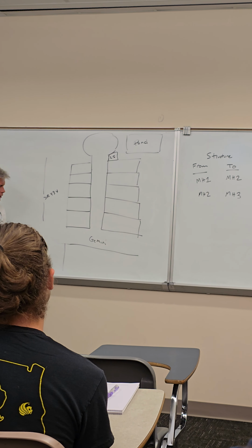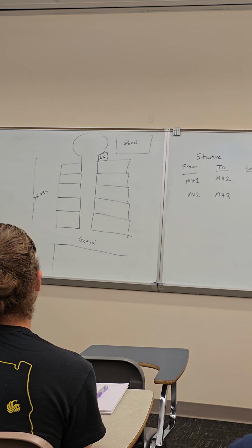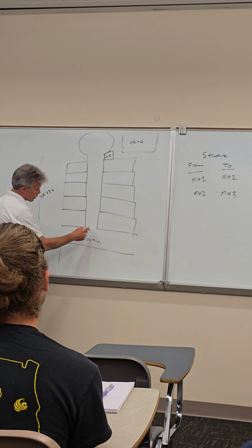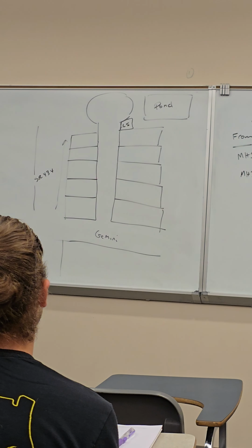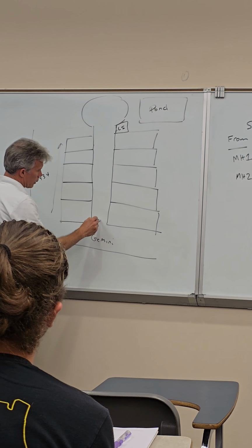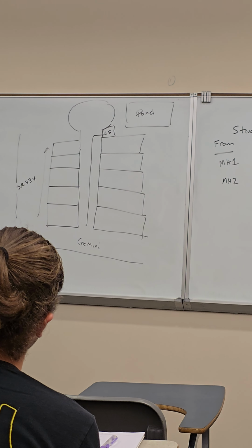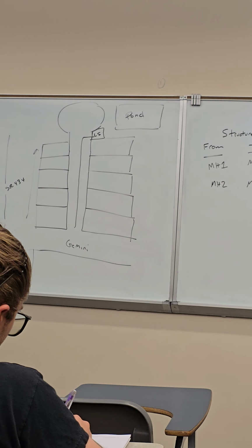You're gonna design a sanitary system, and the assumption is that you have a lift station in the end of the cul-de-sac somewhere. So the slope of this road is generally in that direction, right? So you want to be able to design a sanitary system that collects whatever wastewater you have and takes it to the lift station. So that's the task, okay?